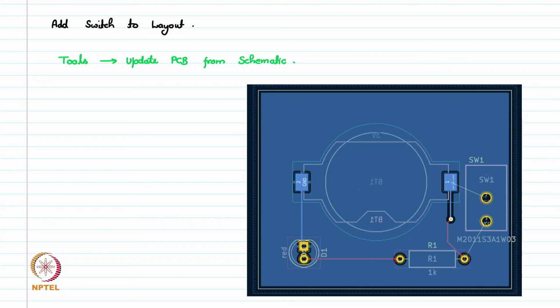Once we click on it, in the earlier PCB which we designed in the last lecture, this extra footprint will be visible, which is our newly developed switch. This has a footprint something like this. Now all these red nets are already connected by electrical layers. These extra red nets will be visible here.